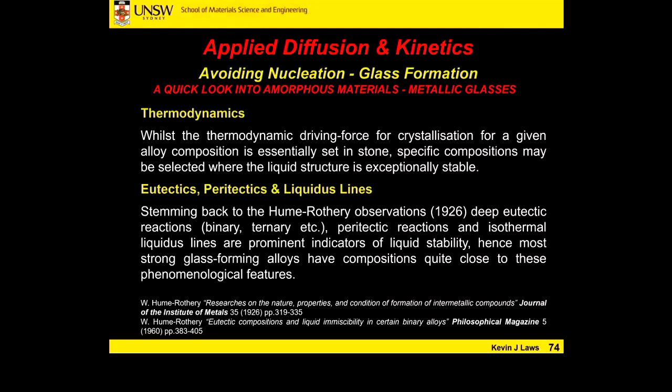So these cluster structures, short-range order structures, are very, very stable at that composition. Thermodynamics down here is described. Thermodynamics up here is never described. If you actually go back and look at Josiah Gibbs' formulas and theories on thermodynamics, one of his first two assumptions is all atoms are the same size and liquids are random. Both of those statements are incorrect.